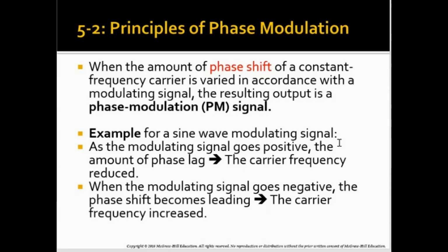As the modulating signal goes positive, towards the peak, meaning increasing, the phase, for example, is lagging, meaning your carrier lags the center carrier or center frequency.